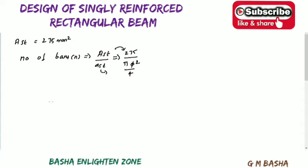So the area of one bar will be pi dia square by 4 and this capital area of the steel will be 275. And here in trial number 1 you can assume the dia of bar. The minimum bar used in the beam will be 8 mm. Already I used to tell that for hanger bars you can provide 8 mm. It is better to take 10 dia bar or 12 dia bar, starting with 10, for the tension reinforcement.